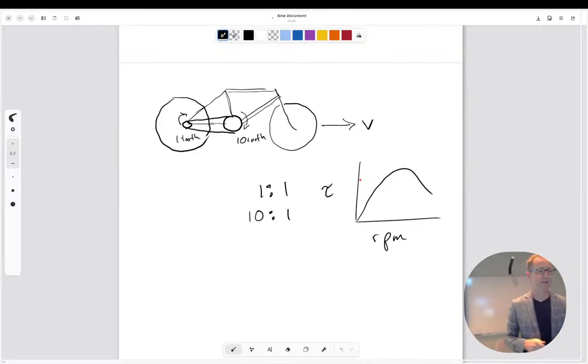What is the torque? So with dynamometers, usually the faster you run your engine, the more power you get out of it. But there's an optimum: at a given RPM, you'll get the most torque out of your engine. For diesel engines, it's much lower. For gasoline engines, it's a little higher. Electric engines, super low. They have tons of low-end torque. So low RPM is what you want for electric engines. So you create gear ratios in order to get the wheels to move at a different speed.